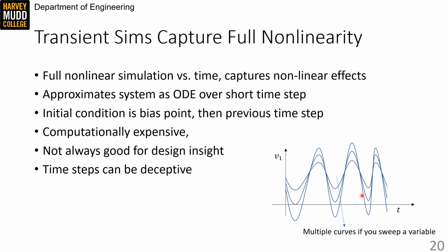Transient simulations also depend on the DC operating point of your circuit as an initial condition for the transient, which is calculated by finding the evolution of a series of ordinary differential equations that approximate your system. That means that you should carry out a DC simulation before a transient to make sure your circuit is at the correct operating point. I also recommend carrying out an AC simulation before a transient to glean design insight, but that depends a little on situation.